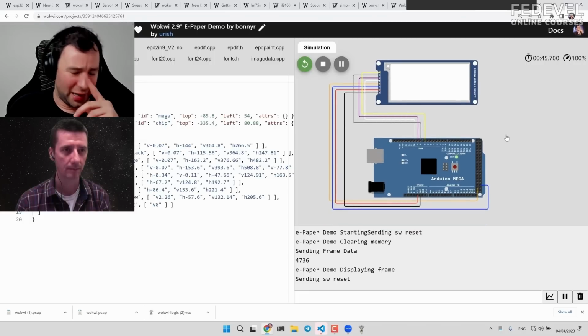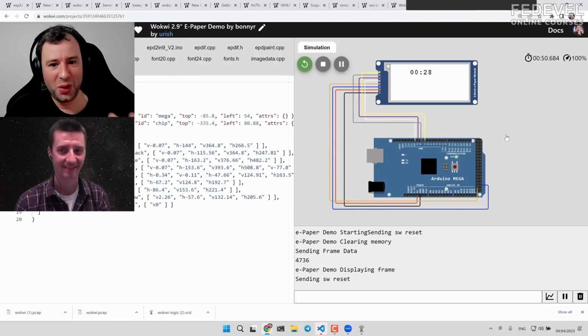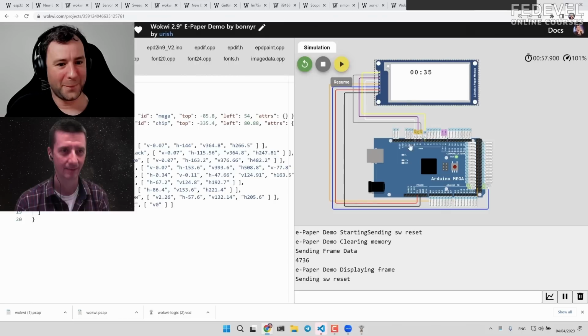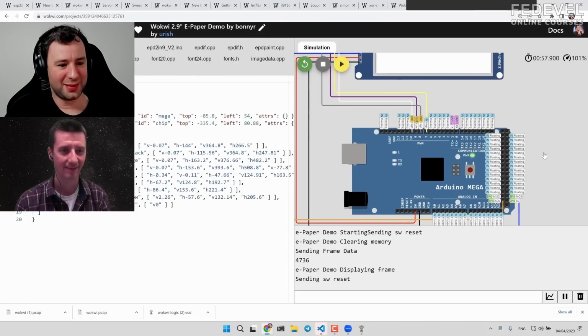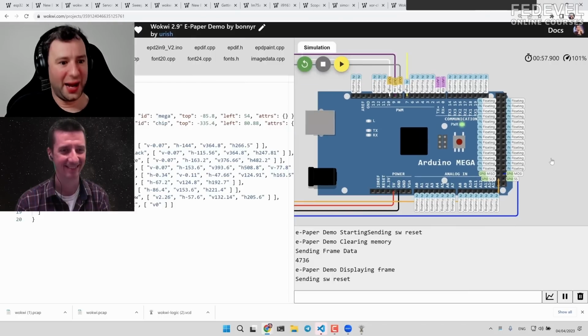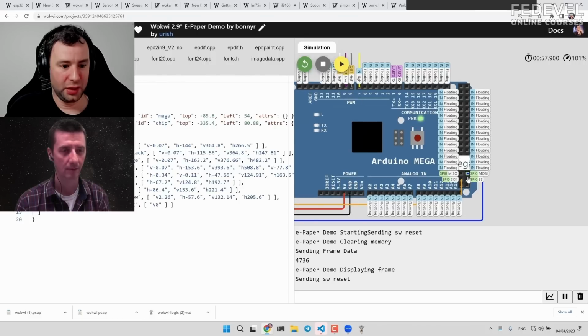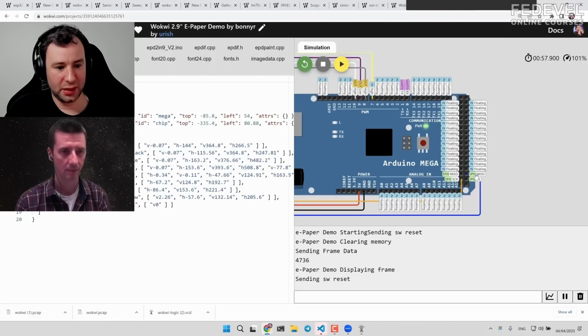And, you know, I just figured out we missed one very important feature. We always showed what happens when the simulation is running, but what happens when you pause the simulation? Oh, you can see how all the pins are configured. You can see every single pin on your microcontroller, its state, input, output, high, low. And if it's configured as a peripheral, like here we are using the SPI, you can see the configuration.